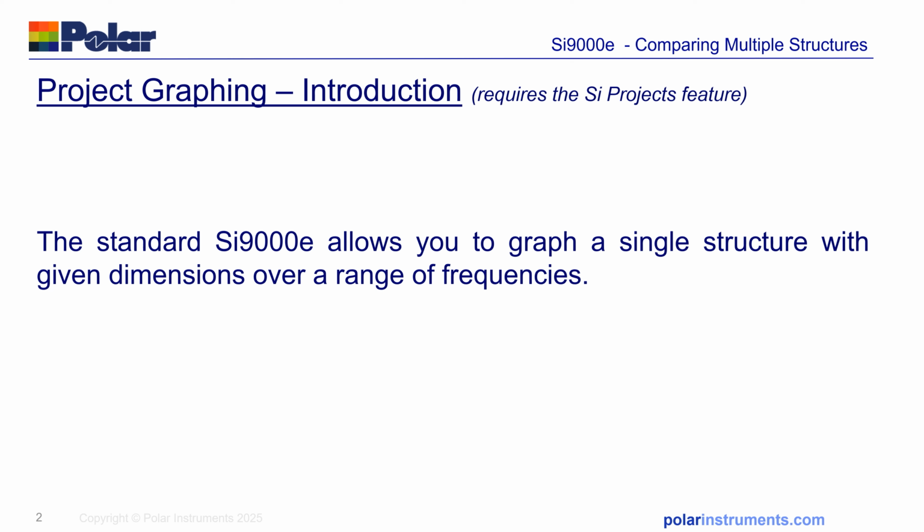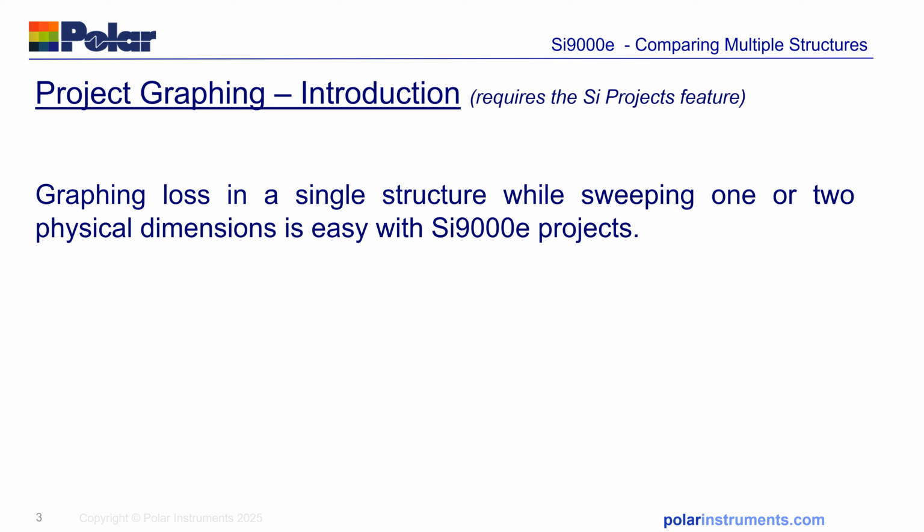If you're familiar with the standard Si9000e, it allows you to graph a single structure with given dimensions over a range of frequencies. Adding the project graphing capability allows you to sweep one or two physical dimensions, and it makes it very easy to look at a number of scenarios as you change different dimensions over a wide range of frequencies.